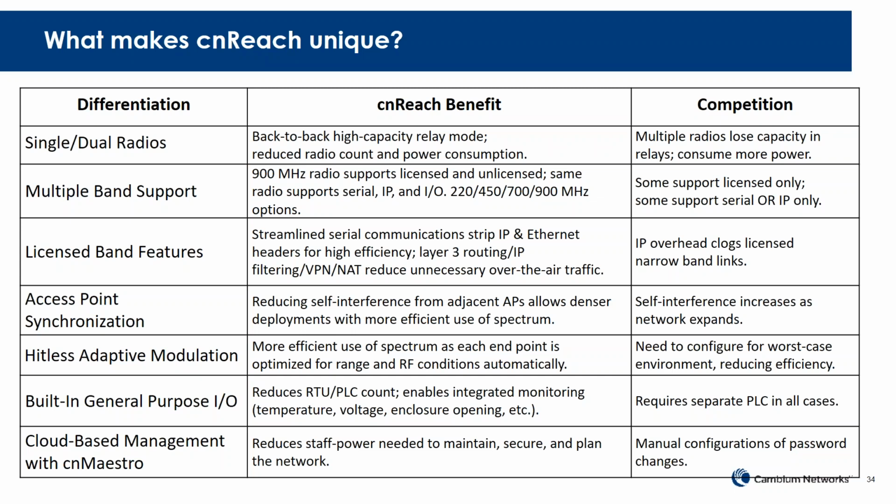If you have multiple towers that are in different areas, say a few miles or a couple of kilometers away from each other, and you still want them to be synchronized, you can use Cambium's UGPS module to synchronize multiple towers. They'll use that GPS signal to get a 1 pulse per second precise timing signal coming from the GPS satellite, and use that as the synchronization.